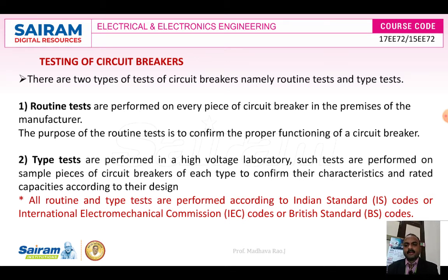And the type test. These type tests are done at high voltage laboratories, performed on a small piece of the circuit breaker of each type to confirm their characteristics and rated capacities according to their design, that is, whether the operating performance is correct or not.